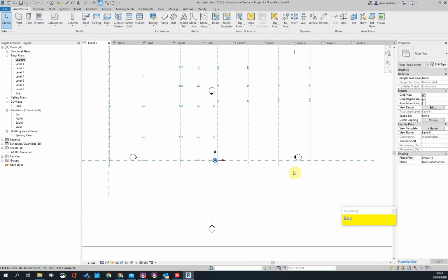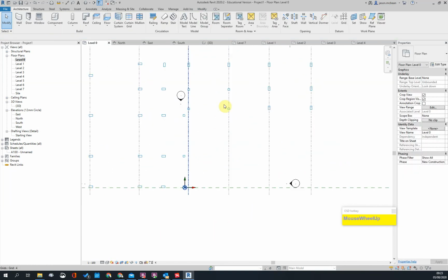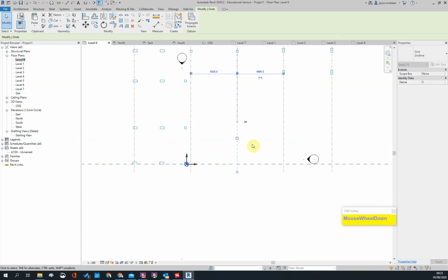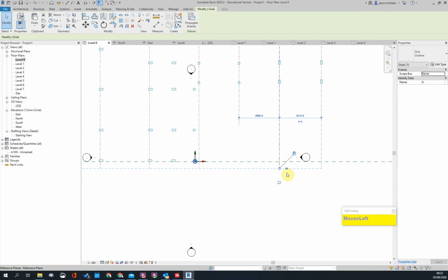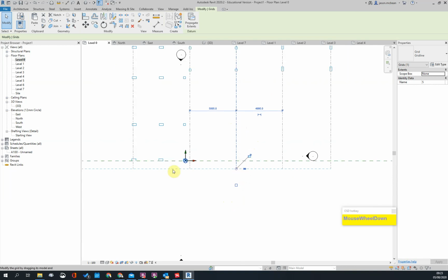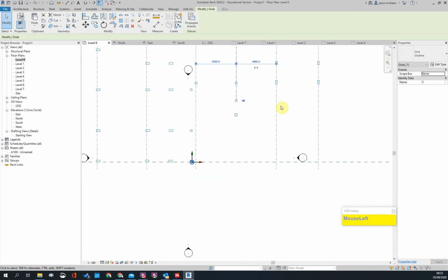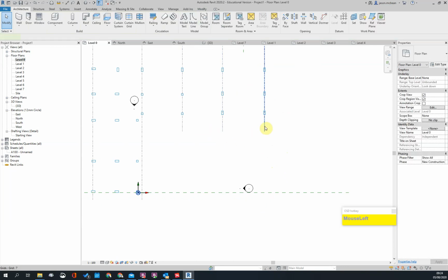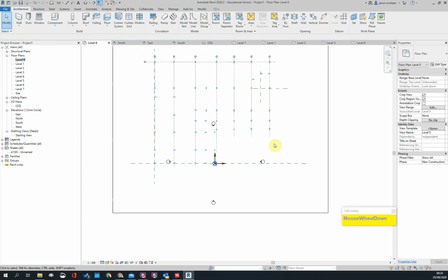Once you establish a relationship, for example with these grids, because they'll stop short, you can click on the 3D and pull it back. Likewise with this. Let me just do that again. I want to use the 3D extents. If you click the 3D extents, you unlock it so it doesn't keep the relationship. You pull it back once, and you do the same with this one, and now these will form a relationship here. So unpin it and then pull it back to this line here. Now these three work together, so if I drag this, this will work. This is important.